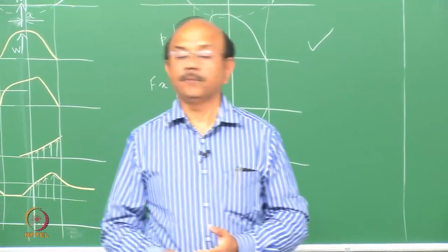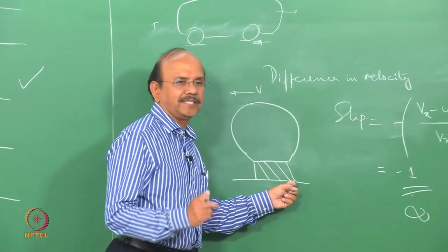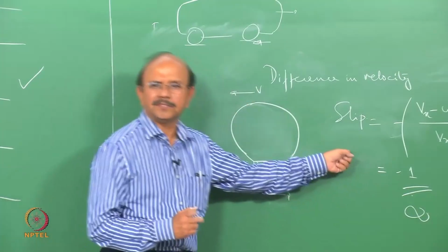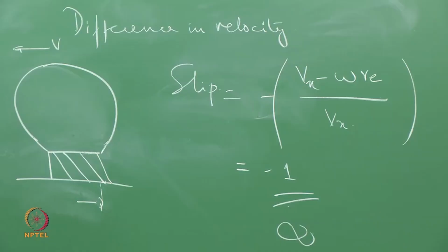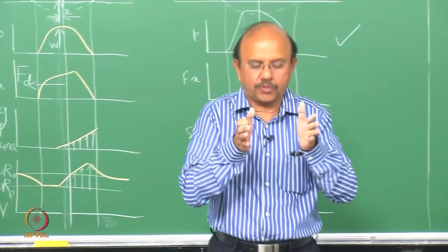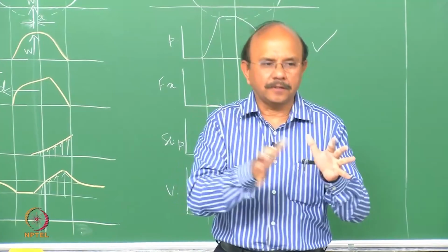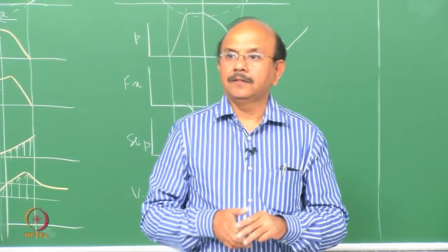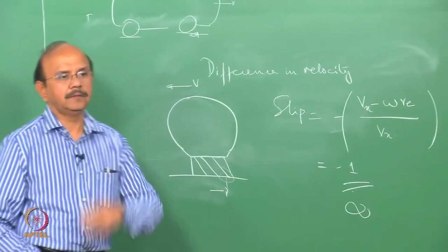That's point number one. Point number two, I want to distinguish between, when I say this slips, I have just defined a slip quantity here. So what is this slip and what is this slip? So I would call this a micro slip, right? There's a micro slip. Okay? This motion is a small motion, just this bristle just moves. Okay? Moves in such a fashion that it comes again to an equilibrium. Okay? Now, this is what we studied before on how mu is developed.